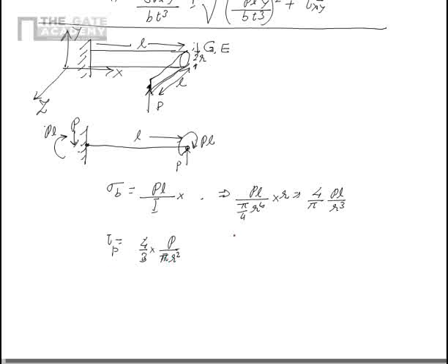If I draw the bar here again, this stress is here at this point, the center, while that stress is here at the top and the bottom fibers. Because this is the maximum bending stress. Bending stress occurs maximum at the top and bottom fibers. So this is the location of maximum bending stress, while this is the location of maximum shear stress because of the applied shear force.